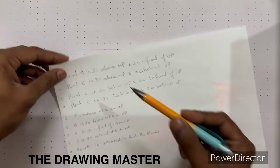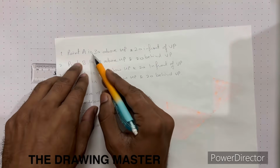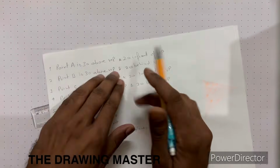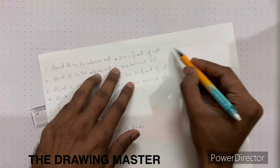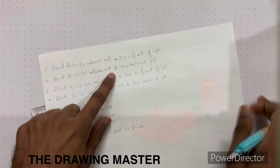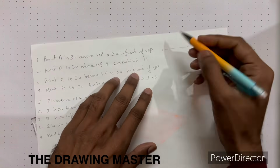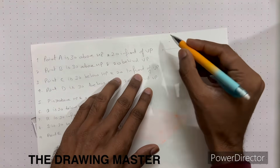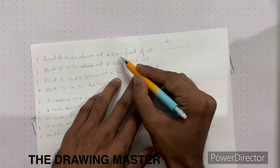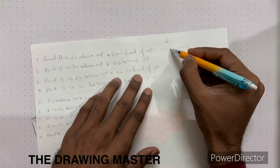So it is given that point A is 30 above HP and 20 in front of VP. So above means above the reference line, that we have seen now. Above means above the reference line and is always front view. 20 in front, so in front will go down.